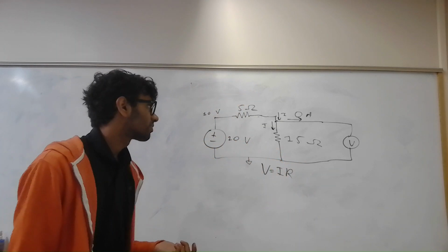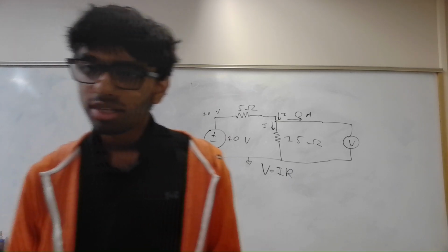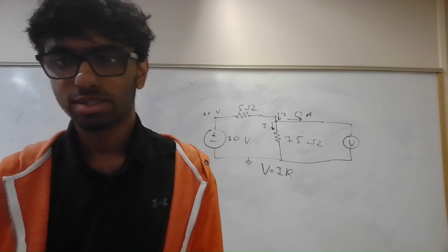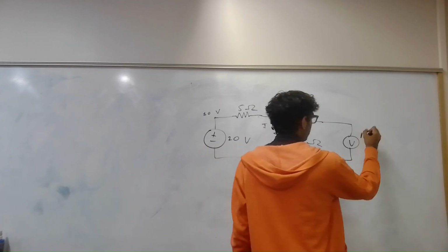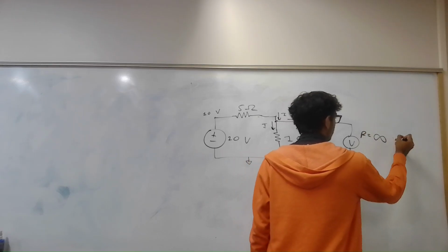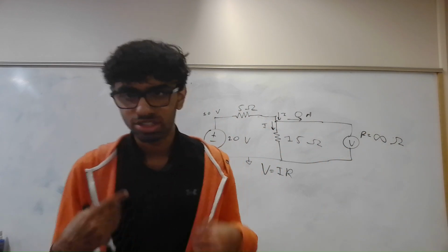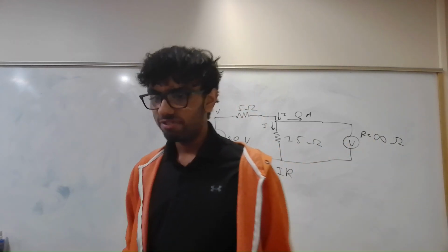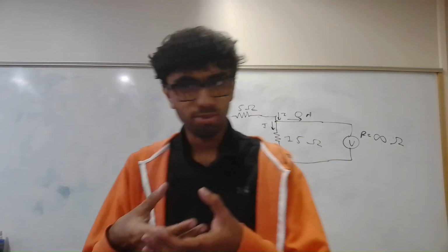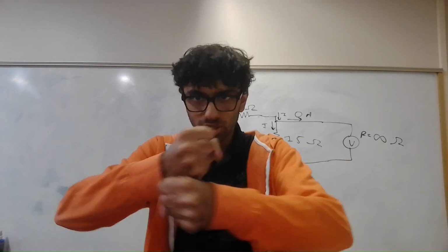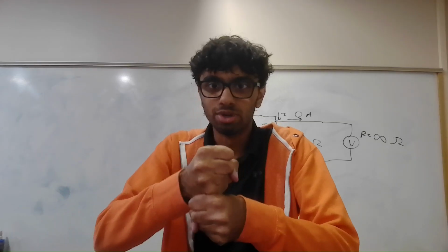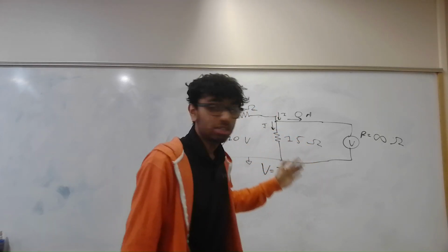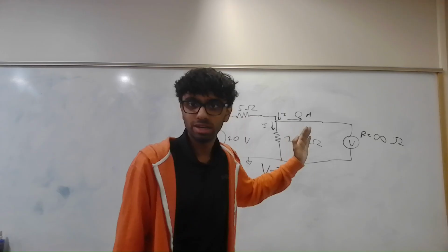And so, what property gives it the ability to have 0 amps? Infinite resistance, okay? So R equals infinity ohms. Now, of course, it's not actually infinity. It's just a very, very large number, so much larger than that resistor. But think about what infinite resistance means, right? If I have a pipe with water flowing through it, and I constrict that pipe, I just close it off entirely, so tight that nothing can get through. Infinite resistance has led to no current flow, right? So it's almost as if I've broken the circuit right there.